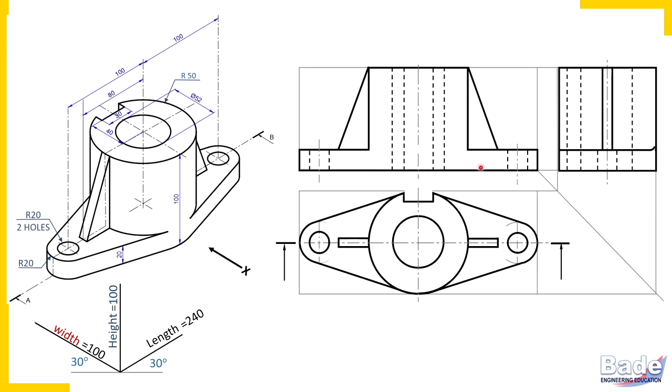Cylinder and the base plate, there was a boundary here, but I have removed that, and I instructed you that when two portions get cut by a cutting plane, the boundary between the two portions of the object does not appear in the sectional view. Then why must we not erase this boundary or this boundary? Try to understand. This is a thin triangular plate.